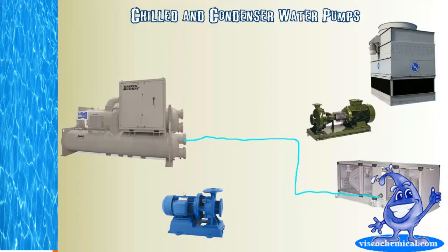And the reason why they do that, and it'll help you identify what piping is what, is that way when you fill this coil with water, you always want to have the outlet of the water coming out the top of the coil. You want this to fill up with water before trying to pull it out. If you were to supply this coil with water coming in from the top, the water may not actually fill the coil and you'll get air in this coil, which would mean you're not going to get cooling on the upper portions of the coil, and water would flow in and then come down and get sucked out the bottom. So the reason why they fill it up from the bottom is that way you make sure you pressurize the coil and get all the air out of that coil.